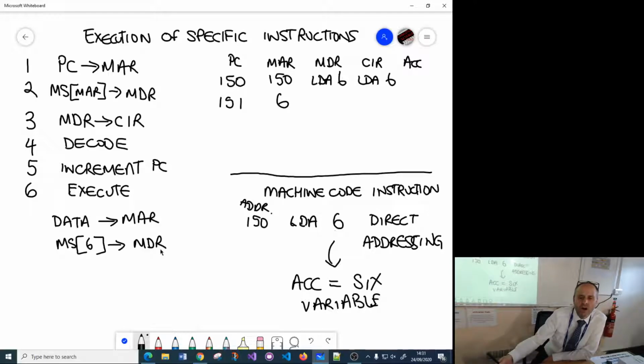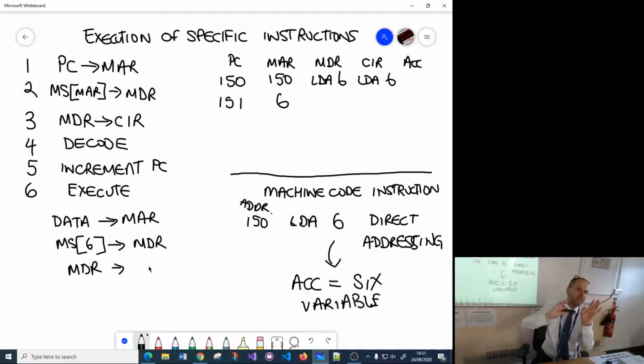So our instruction, we decoded it and it said load to the accumulator. So we can now transfer that value to the accumulator. So what transfer are we wanting to happen? What register to what? Is it MDR to accumulator? Yeah. So we say transfer. So the control unit is kicking signals down the control bus saying, right, okay, MDR, you open yourself. Accumulator, get ready for a value to flow along the internal data bus, the one that's on the CPU die. So that this happens. At that point, we've finished executing. So we do our final check for interrupts.